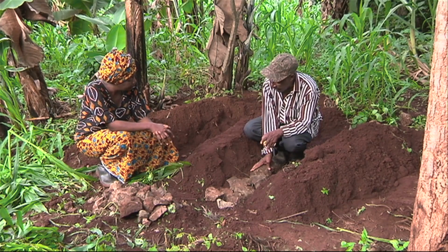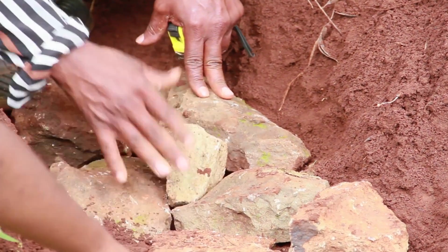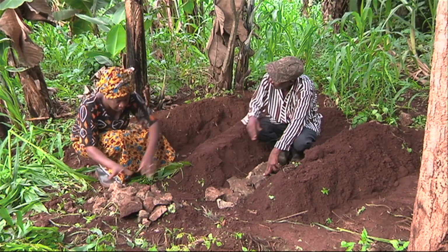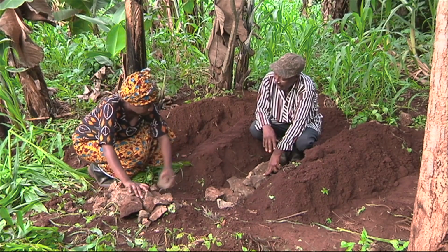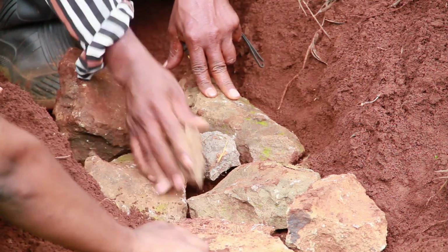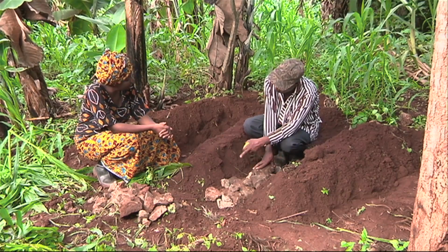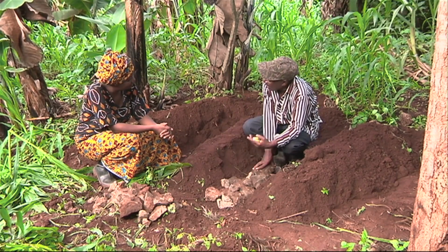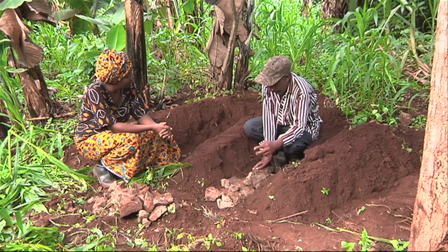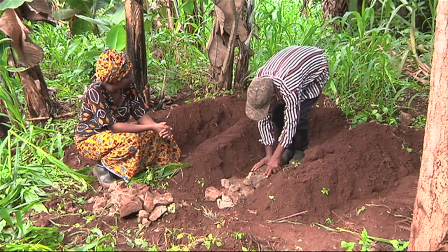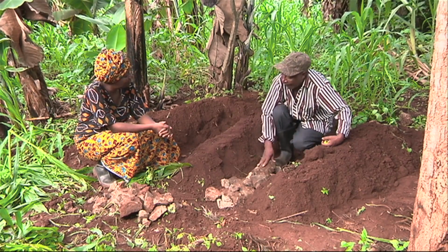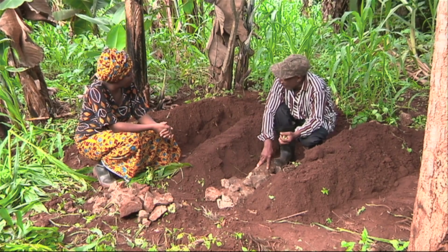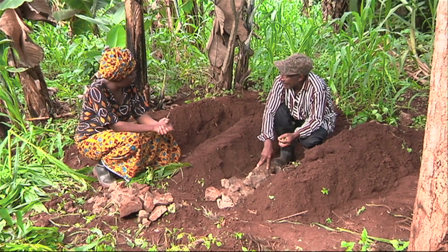After then you can place the small stones. Here we are. These small stones act as a filter to prevent the run of water. And as concerning the planting procedure, Judy, the stone bunds are used to rehabilitate the infertile soil and degraded land. So, in order to achieve that objective, we combine the stone bunds with the zai pits. Thank you very much, Francis.